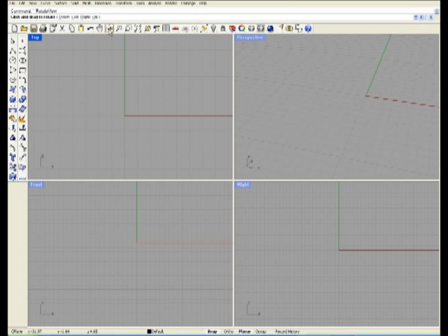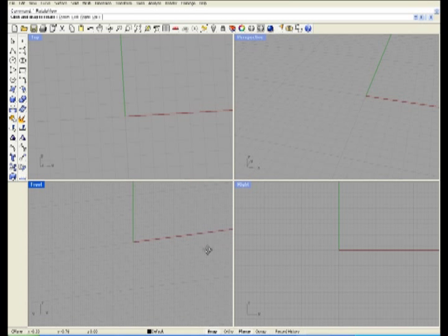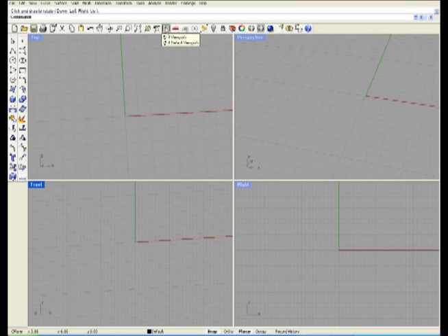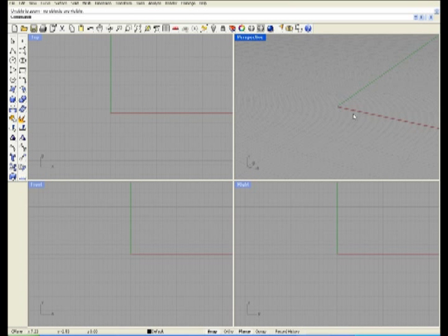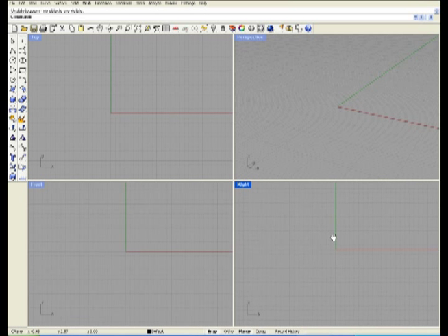Now this rotate option, you can use on any of the views, like top view. You can rotate. You can also rotate the front view. Okay, but I don't recommend you to do that because we need these 3 planes to be completely perpendicular to each other. So in that case, I'm going to double click on 4 viewports again, and this is how it is. Okay, so we know how to move around our software right now.